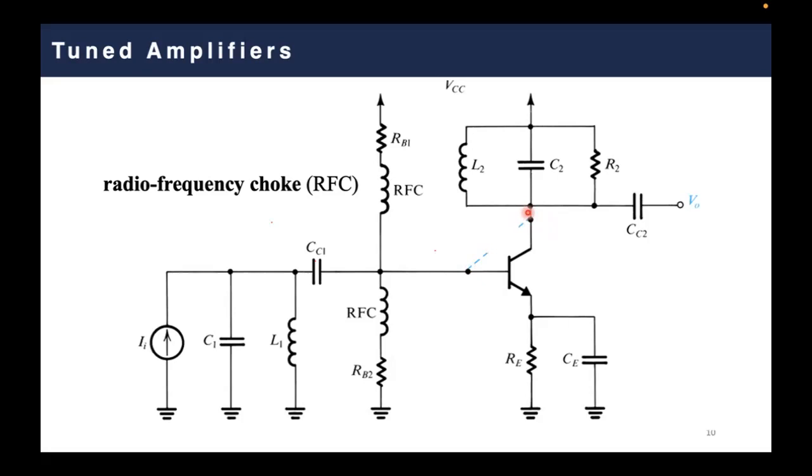Once you have an increasing depletion region, it means typically you have a capacitance. And again, this capacitance is connecting your input to your output, which is typically the CGD capacitance you see in a MOSFET. So again, it has the same Miller effect. So before going into solutions, how can we get rid of, reduce or eliminate this Miller effect, either in a BJT or a MOSFET? Let's try to think about